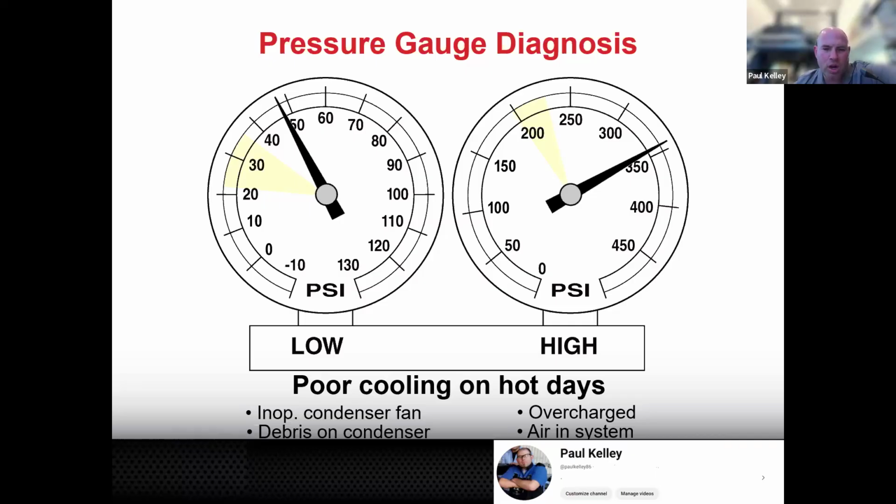There you are in your turbo car and you go to shift and you close the throttle real quick. Your turbo's still spooled up. The turbine and impeller are cranking and you just close the throttle valve. Where the heck is all that boost that it's making going to go? Well, it's going to go out your blow off valve.